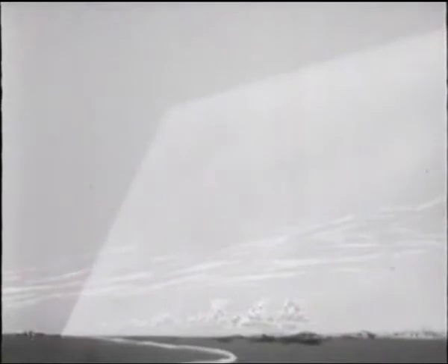However, today's air traffic control requirements demand more, much more, than the position of an aircraft. It must be provided also with means for the immediate and positive identification of an aircraft. Secondary surveillance radar provides this means. It can identify and monitor even a very small aircraft at long range and at great height, provided the latter is equipped with a transponder.